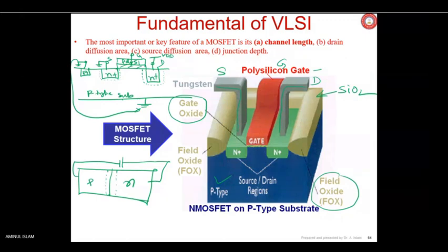So this happens. If it is variable and you are increasing the value from 0.5 to say 1 volt, what will happen to the depletion layer? Will it remain the same or, reverse bias you are doing, so it will increase. So that happened here also. Initially VDS was very less, 0.3 volt or so. You have increased it to say 1 volt. What will happen? The depletion layer around it will be increased.